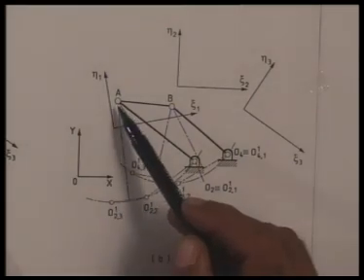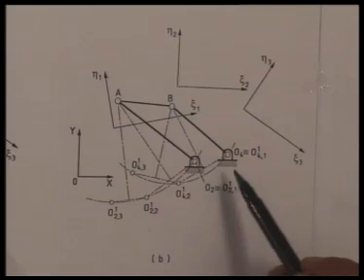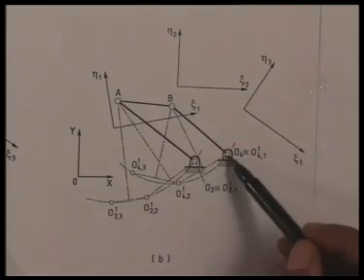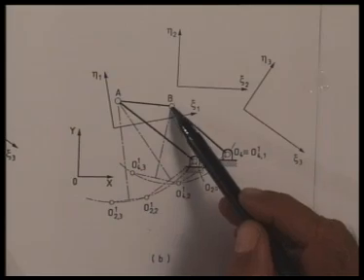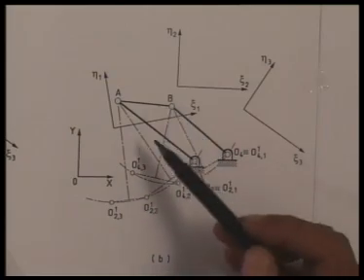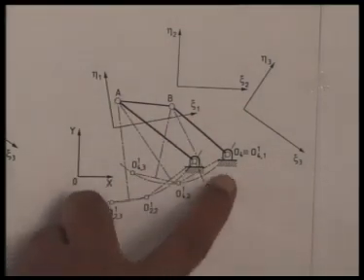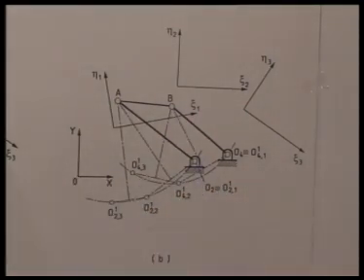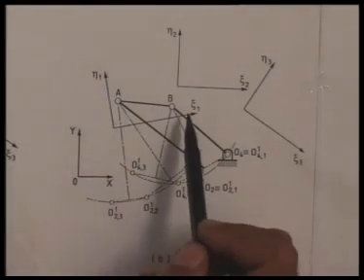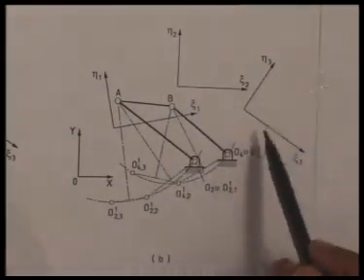This is what I call A. Similarly, the center of the circle passing through the three inverted positions of O4 is B, and that is the other moving hinge on the coupler. So the problem is solved: O2 A B O4 is the required 4R linkage, which when moved, the coupler moves from position 1 to position 2 and position 3.